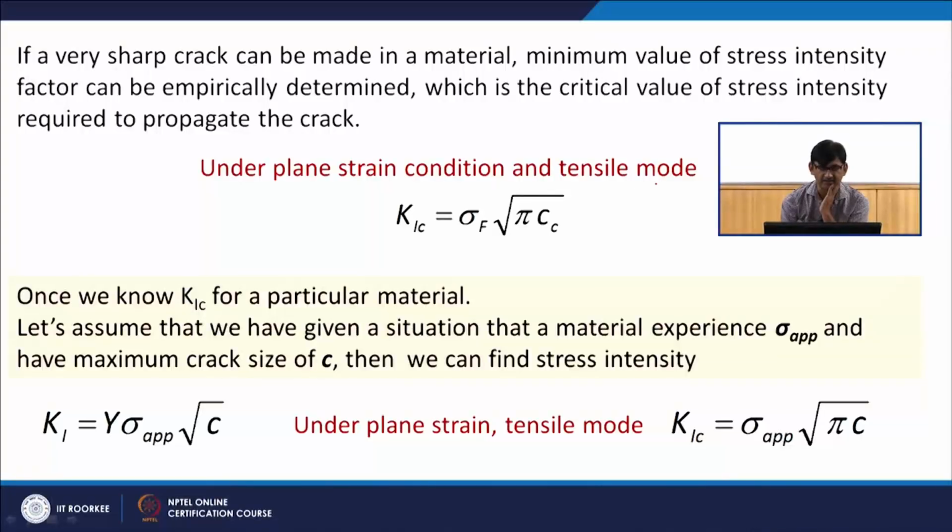So, under plane strain condition and tensile mode, which is K1C, I will find out, for a particular crack length, what the fracture stress is going to be. By doing this kind of experiment, empirically I can determine the critical value of the stress intensity factor. So, for a given material I will get that.